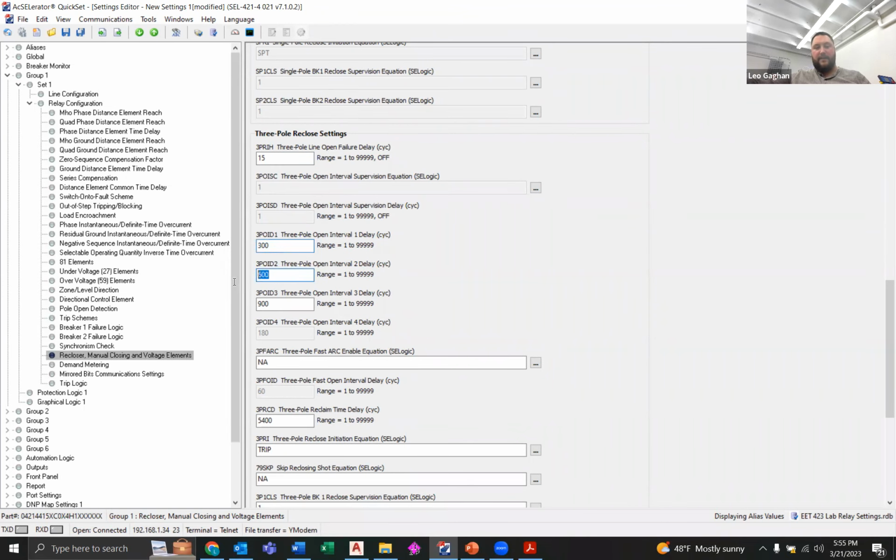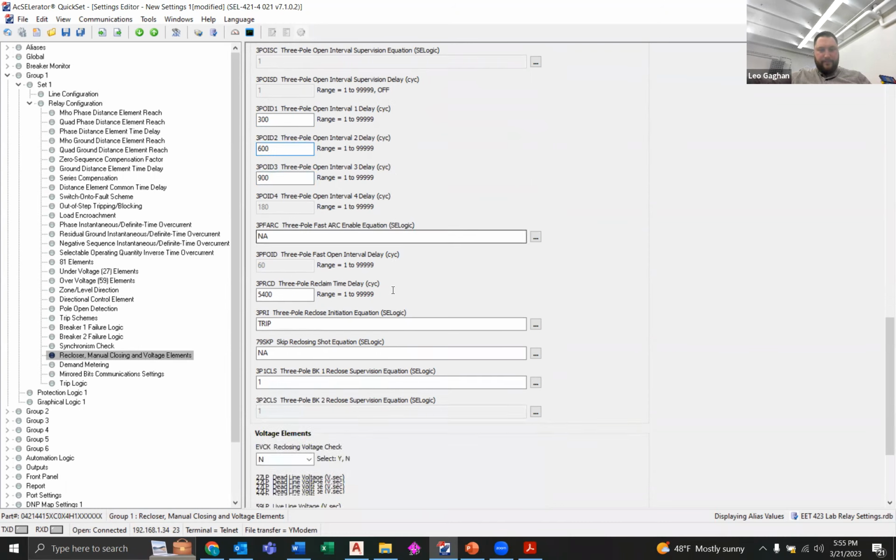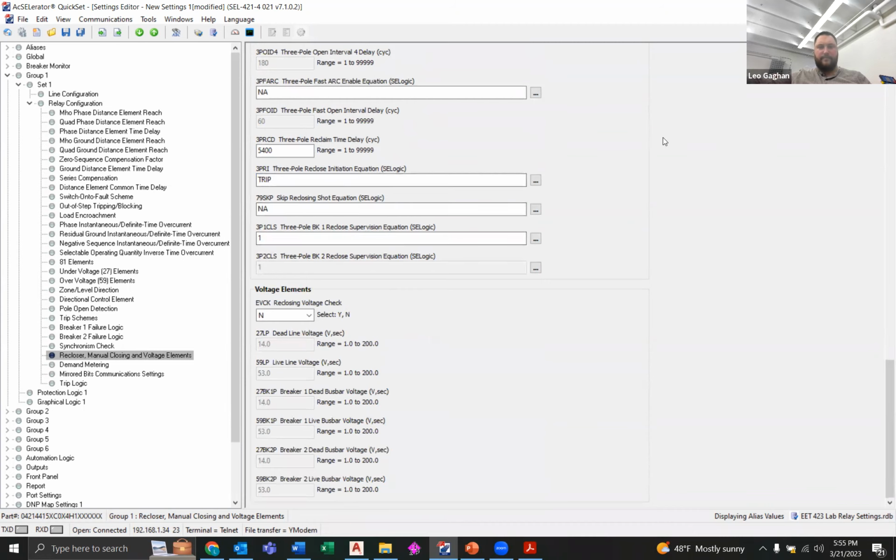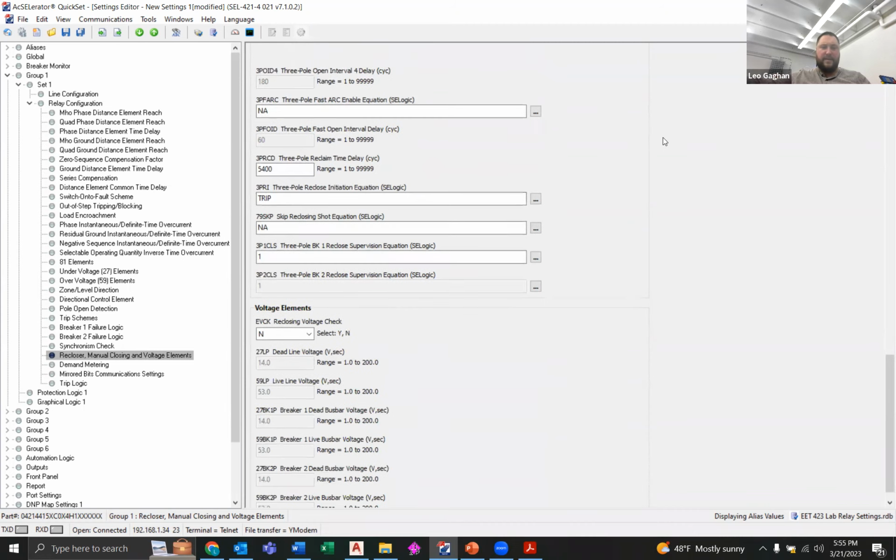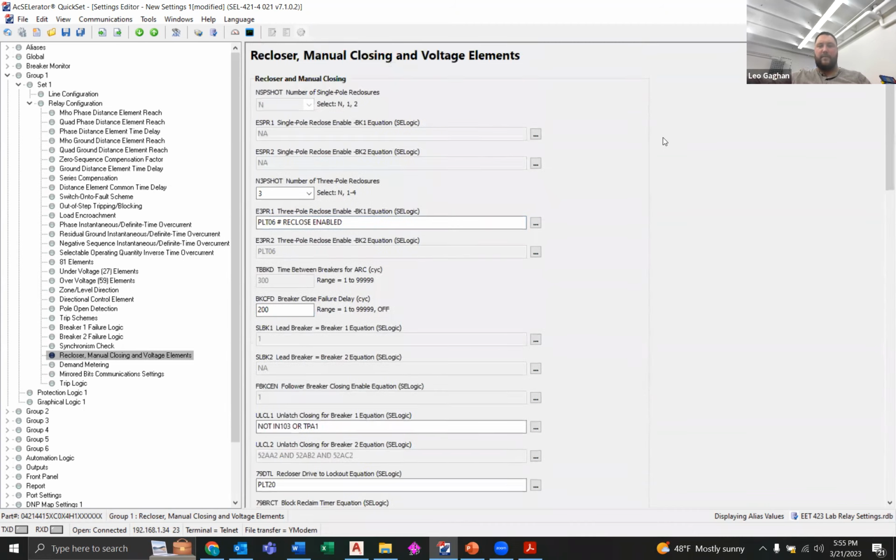Again, they were 5, 10, and 15 seconds. I probably could have stuck with the 15, 30, and 45. We'd still be going through the logic. But yeah, I guess those are some of the basic settings and where you might set them for the reclosing.